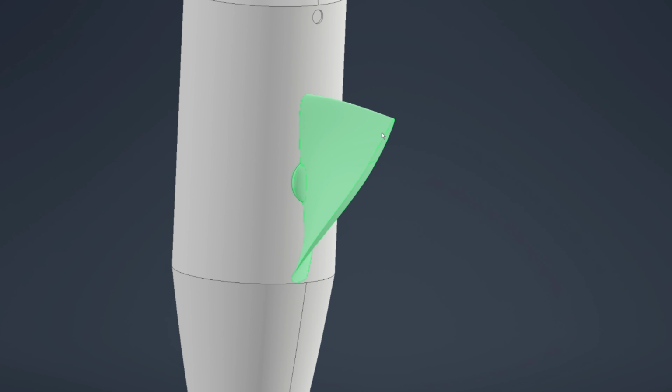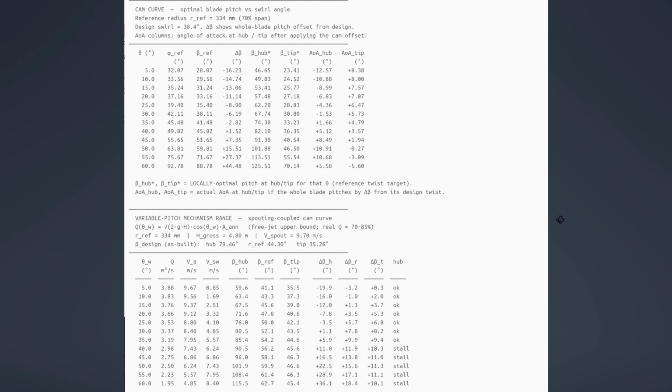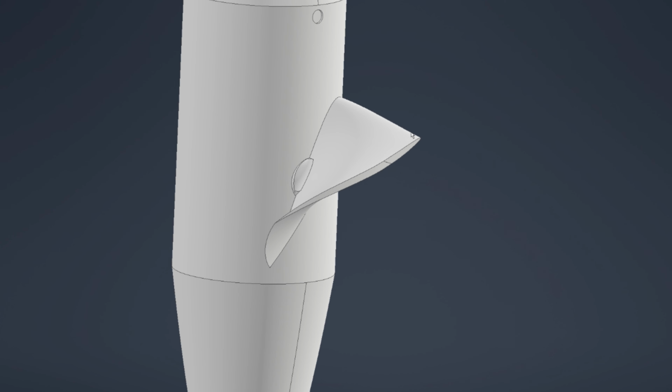Job 1. The big swing. Our swing is measured at about 0 to 17 degrees. The big swing matches the swirl. The wicket gate sets how hard the water spins before the runner. Change that spin and the direction of the flow arrives with it. So the blade rotates to follow, roughly across the same 0 to 17 degrees as the gates open and close.